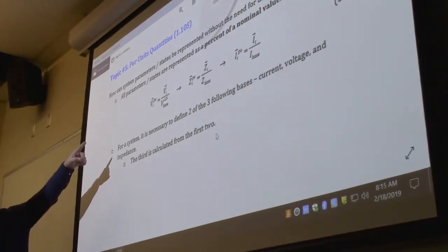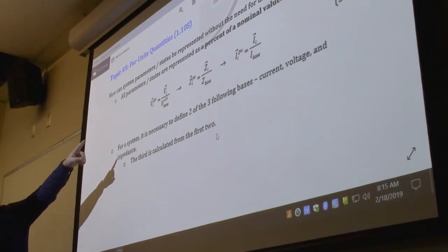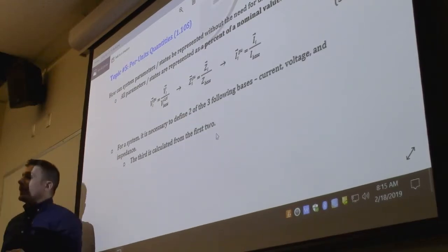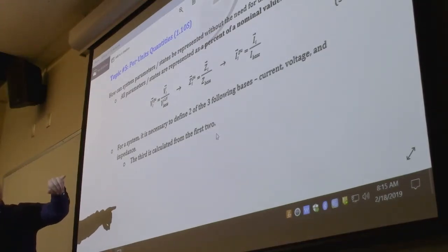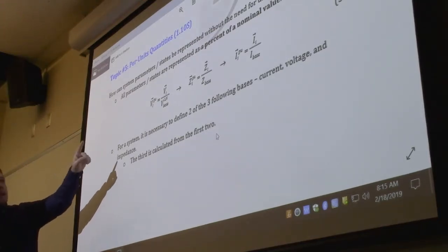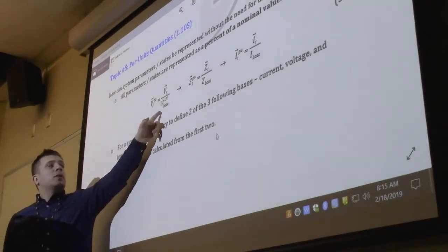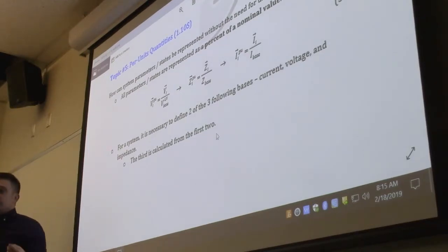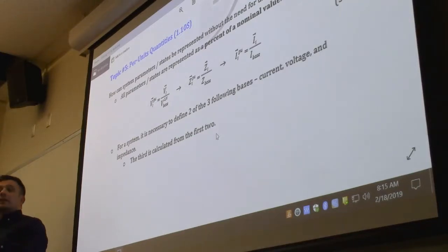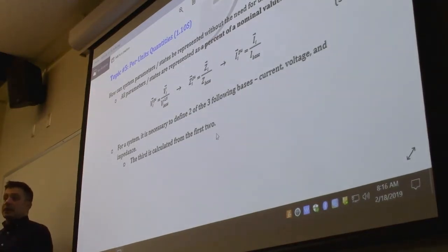Voltage in per unit is equal to the voltage in actual units divided by whatever the base is. Same thing with impedance, same thing with current. You have to be careful whether your voltage is a line to neutral voltage or a line to line voltage, because you want to use the appropriate base for that, and they'll be different, okay? If the line to line base is 208, the line to neutral base will be 120, right? You use the same conversions that we learned about last time between the line to line and line to neutral voltages.